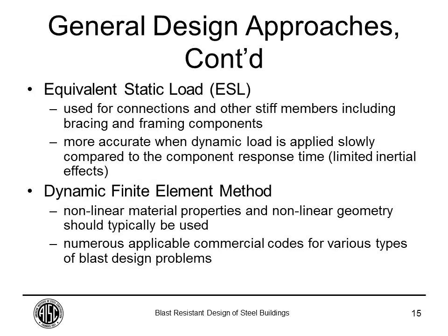This requires the use of more sophisticated analysis tools that can account for nonlinear material properties and nonlinear geometry. It's generally saved for very special conditions. For example, if you're designing for an interior detonation in a mailroom or inside a parking garage, or you have a very close-in charge right next to a column, and you want to take into consideration different modes of response that are not going to be exactly flexural, you might need to employ this method. But for most designs, in terms of typical buildings, single degree of freedom or closed energy solutions or chart methods should be adequate for you to get an efficient design.